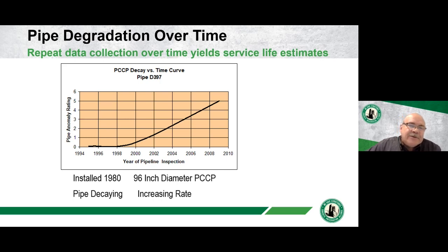Sometimes there are anomaly ratings that are a weighted average of the type of pipe, the condition, and a few other variables, that can be applied to all the different systems to see where the priorities are for replacement.